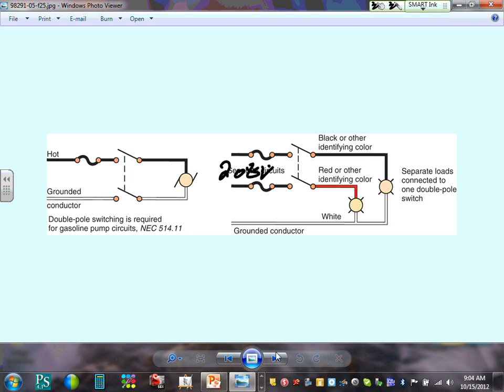Now, Andrew, mistake number one when you start circuiting and putting switches. I've seen it over and over and over. The students come and they say, well, this switch is going to switch two circuits. Yeah, this switch cannot switch two circuits. It can switch only one circuit. To switch two circuits from a switch like this, what do you need to do?